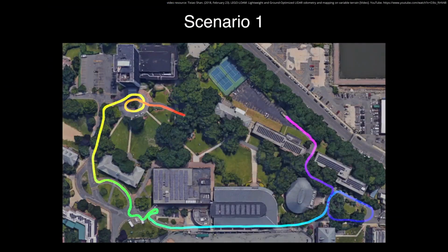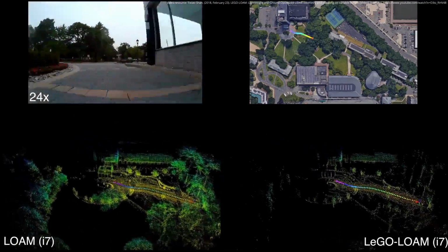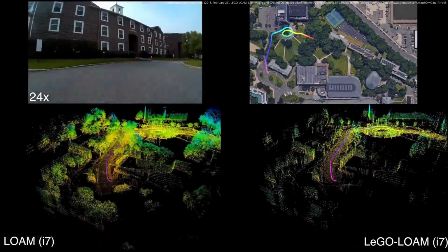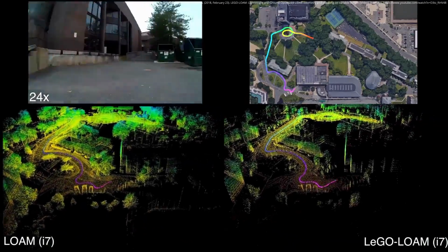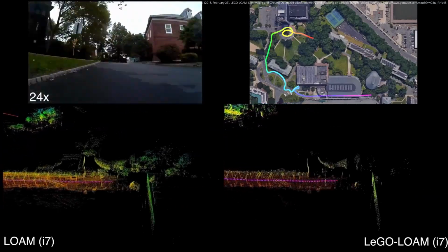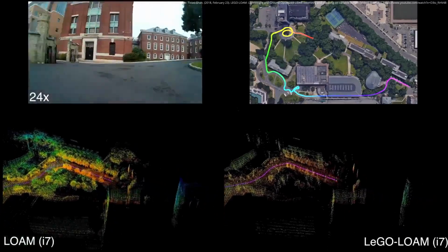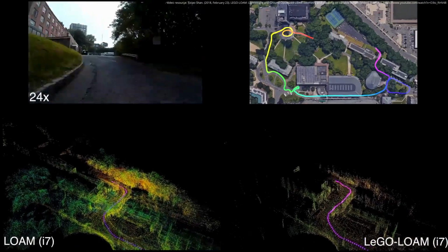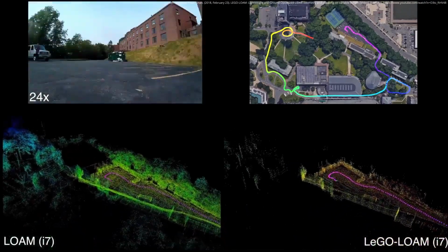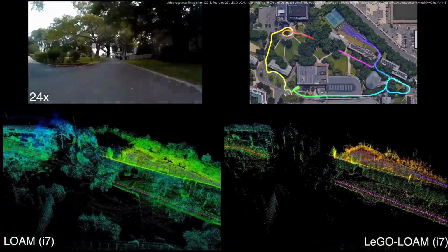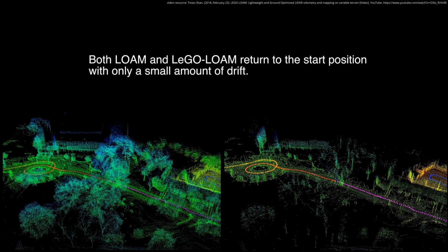For quantifying the performance differences, 3 further experiments are conducted. The first experiment is a demonstration of the low drift pose estimation while driving through an urban environment. The robot moves smoothly without aggressive yaw maneuvers, usually stable features are available and the terrain is even with only smooth asphalted roads. The initial and final position of the robot on this loop track is compared. If the system worked without errors, these should be identical. For LOAM and LeGO-LOAM, the achieved low drift pose estimation works well. The difference between both poses is small. The created map shows a few inaccuracies, but represents the environment still decently.